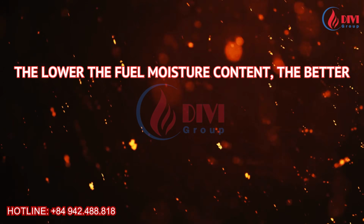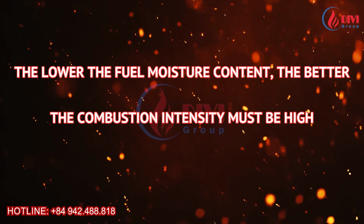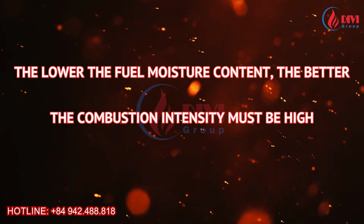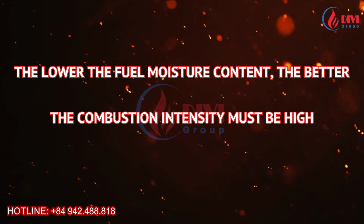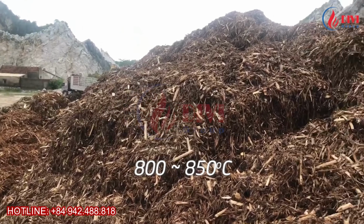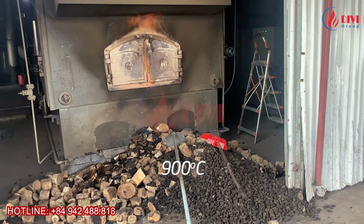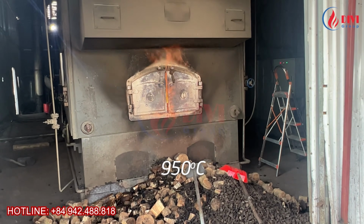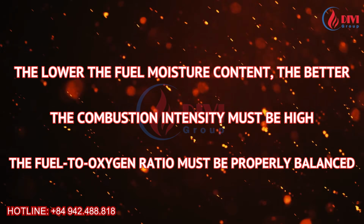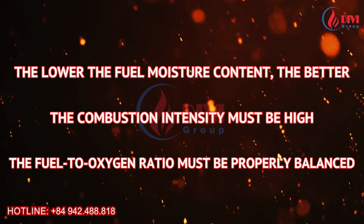The lower the fuel moisture content, the better. The combustion intensity inside the furnace must be high enough, but not exceed the ash melting temperature. For biomass fuels, the ideal combustion temperature is around 800 to 850 degrees Celsius and can reach 900 degrees Celsius, while coal combustion can reach up to 950 degrees Celsius. The ratio between fuel input and combustion air must be properly balanced. Neither too much nor too little oxygen is ideal.